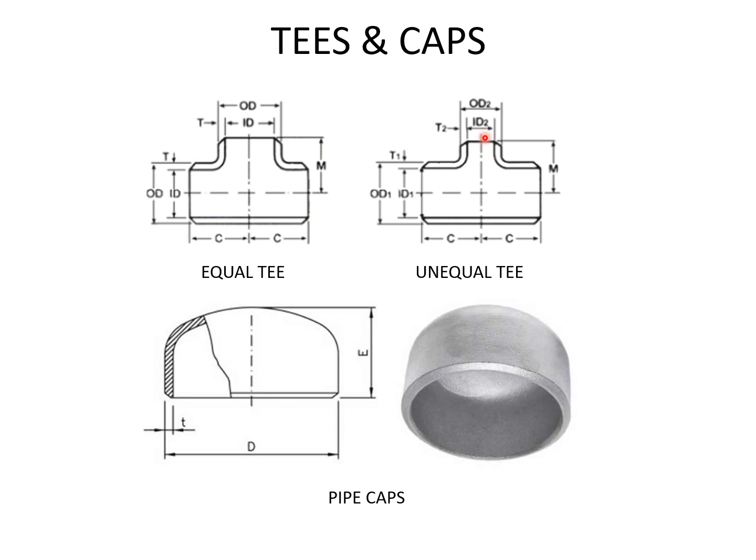For example, if we have a 10-inch pipe, it will have a minimum branch diameter of 4 inch: 10 divided by 2 is 5, and one size less is 4 inch, up to 8 inch. Then caps, these are the pipe caps. These are used at the pipe end.